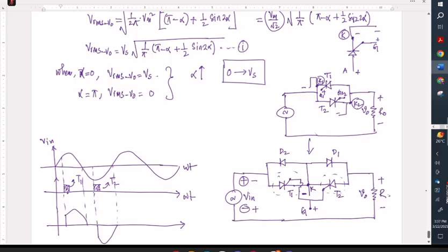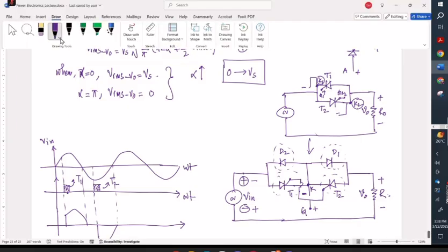So in that case, you can do the same thing with two added diodes, where you don't need an extra circuit for the thyristor. Of course, nowadays you have everything with the triac, where you don't need to use the thyristor. But I am saying, if you have the thyristor, then you have to have two separate circuits. Otherwise, you have to use two diodes so that you can have a single driving circuit to turn on two thyristors. So in that case, now tell me, what should be the current waveform?